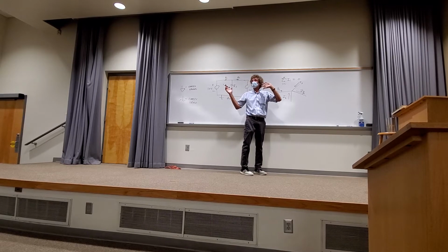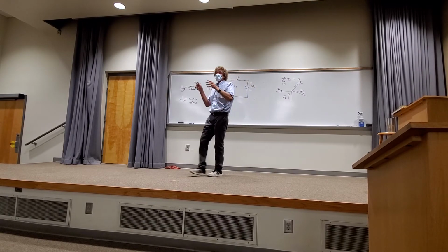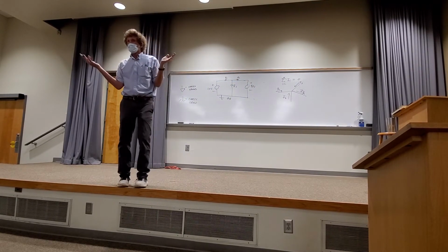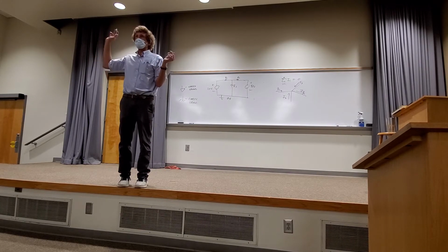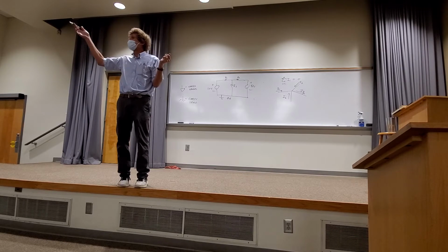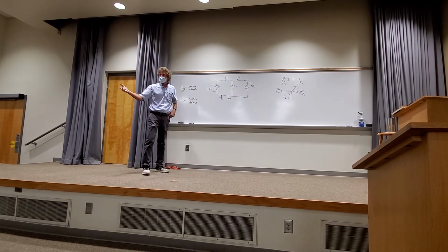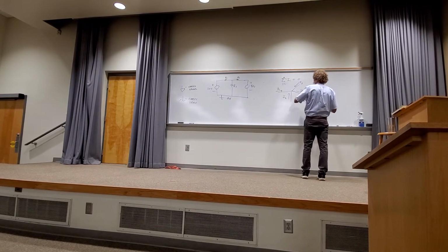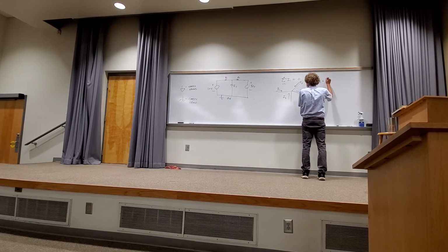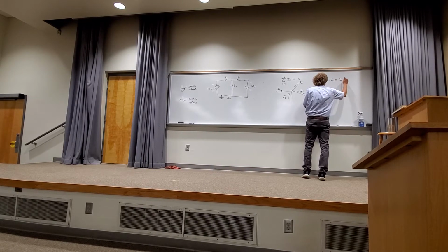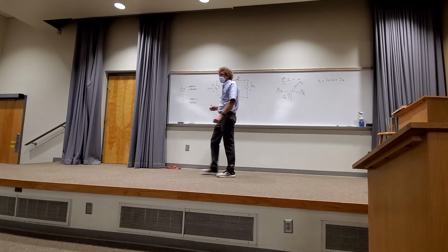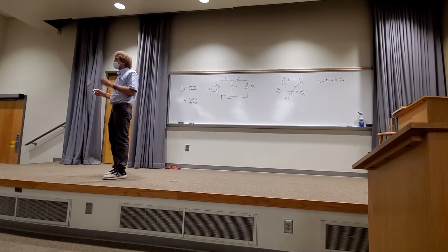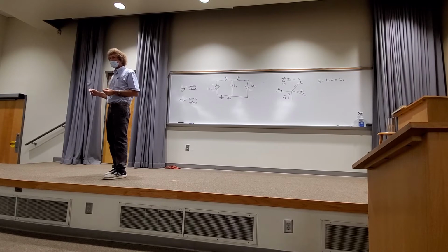The algebraic sum of all the currents into a point is 0, or the way I like to say it, and the way I was taught, whatever goes into a point comes out of it. How many have had incompressible fluid dynamics, or refrigeration? They should have taught that law there. So really, whatever comes in comes out, so I could say that I1 plus I2 plus I3 equals I4. You all see that? You have to have a direction for current, just like you have to have a polarity for voltage. You all with me? And there has to be a reference.